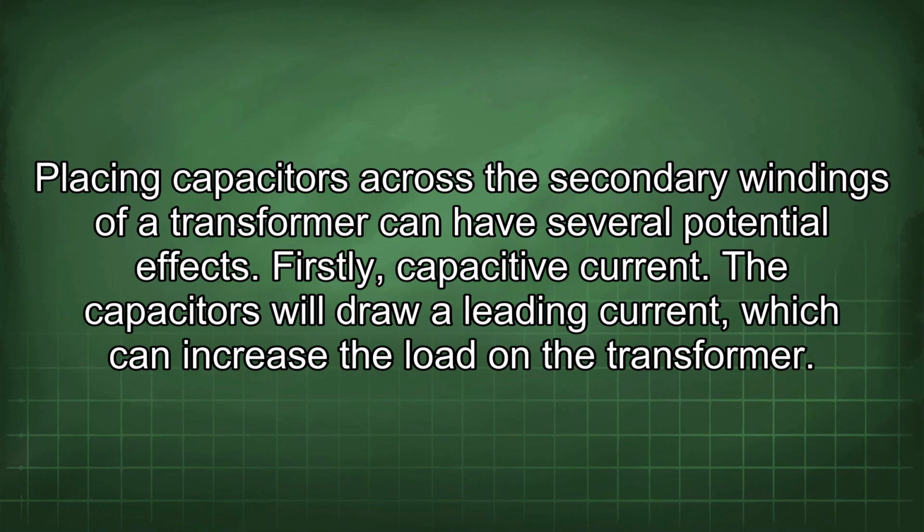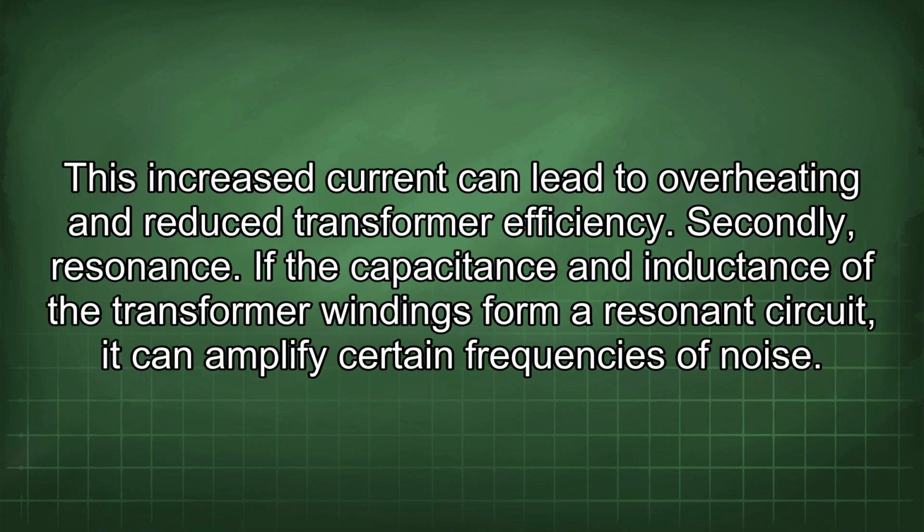Placing capacitors across the secondary windings of a transformer can have several potential effects. Firstly, capacitive current. The capacitors will draw a leading current, which can increase the load in the transformer. This increased current can lead to overheating and reduce transformer efficiency.